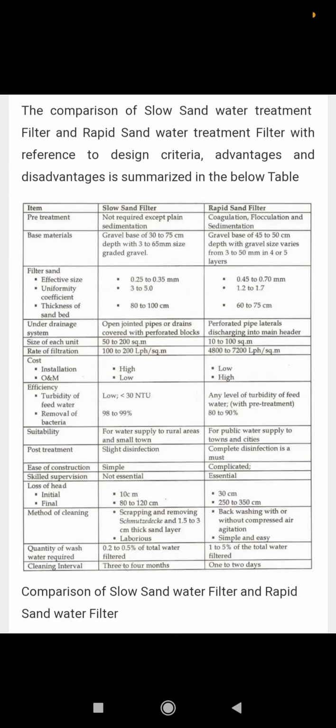Good afternoon. So, in the previous topic, we discussed the different treatment methods for water treatment. In that, we discussed the first, screening, which is used for the removal of floating solids. After that, we discussed aeration. That aeration process is used for the removal of bad odor and gases from the water.